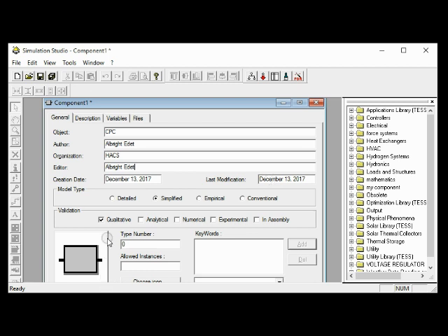Then next we want to see Model Type. Below are a row of radio buttons for entering model type. Detailed models would include the multi-zone building model, Type 56. Simplified models would include such things as curve fit readers or the forcing function component.